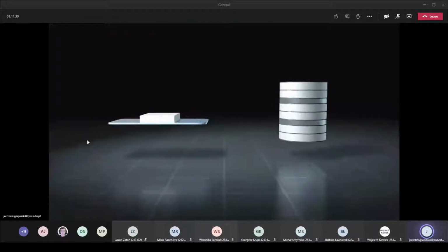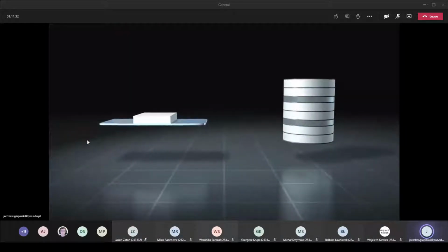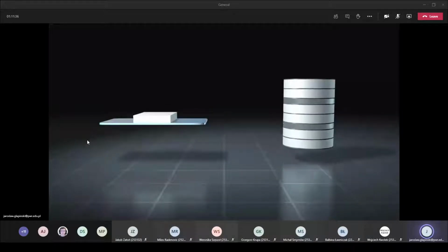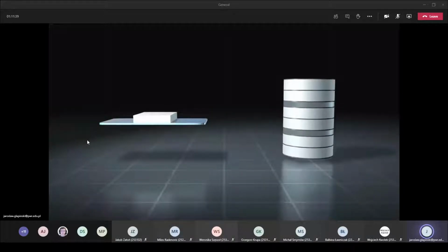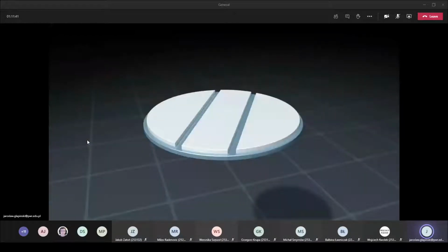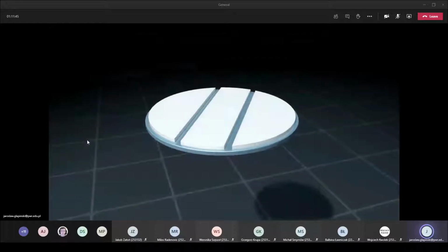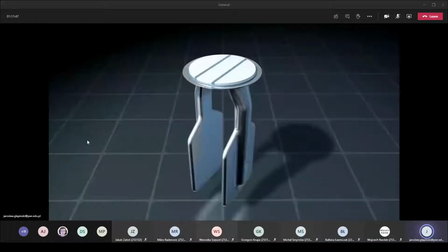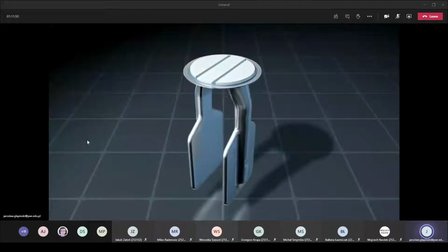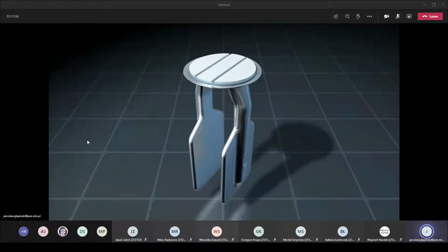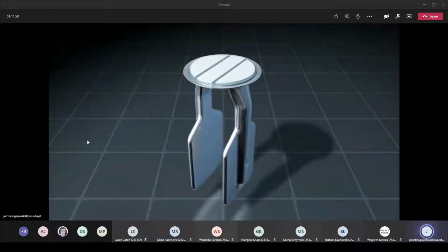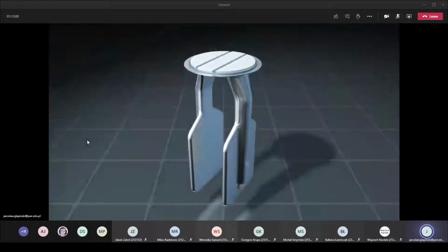There are 2 different piezoelectric drives, the bimorph drive in standard instruments and the stack drive in coated instruments. The bimorph drive consists of 2 discs, a piezo and a ceramic disc, which are connected to each other. At the same voltage, the piezos are compressed and the ceramic disc is bent. At different voltages, the piezos expand again. This causes the oscillations of the fork.